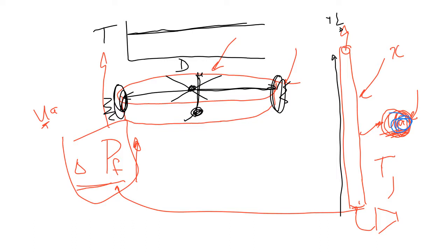But in the middle, the heat must dissipate through the fluid, or through the packing if I have a packing, to the sides of my reactor. That is one of the reasons why you will not build pancake-like reactors.